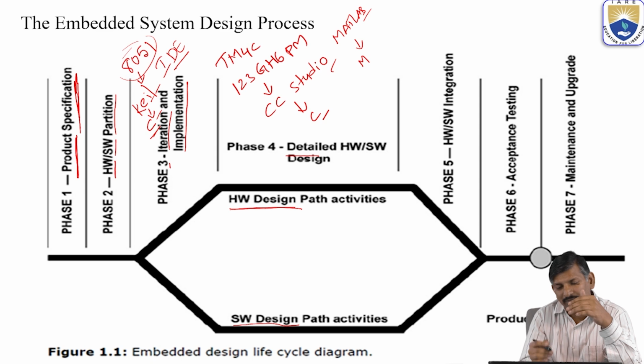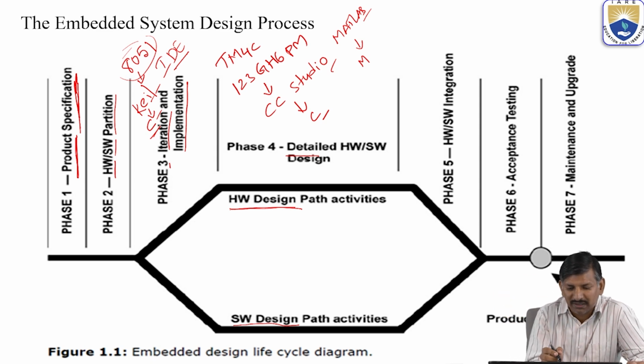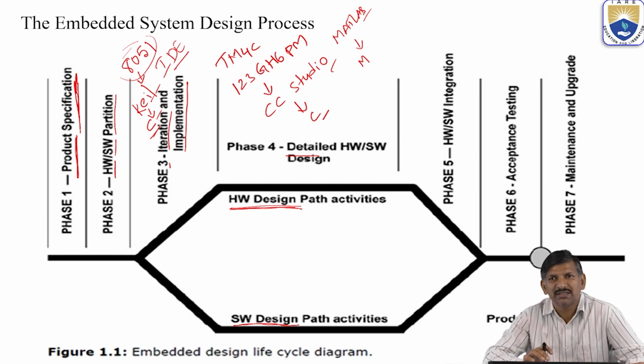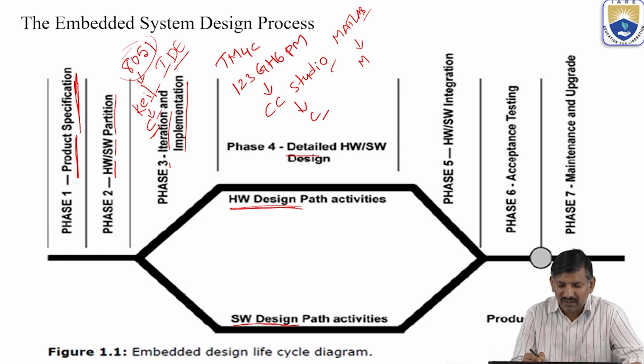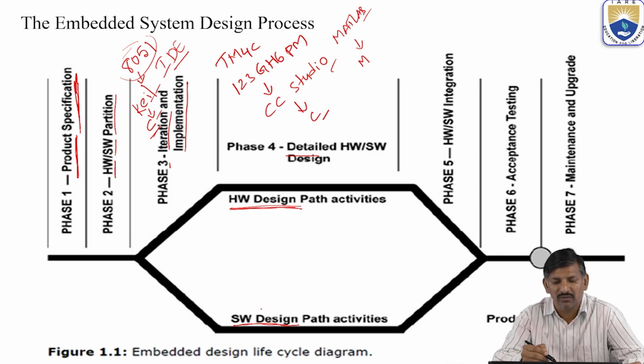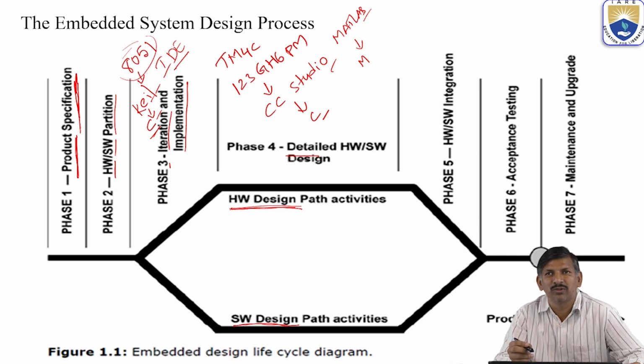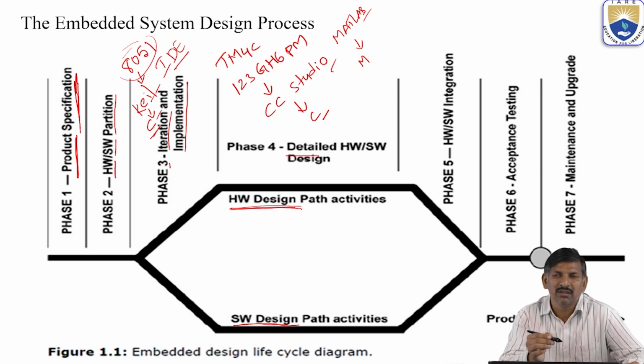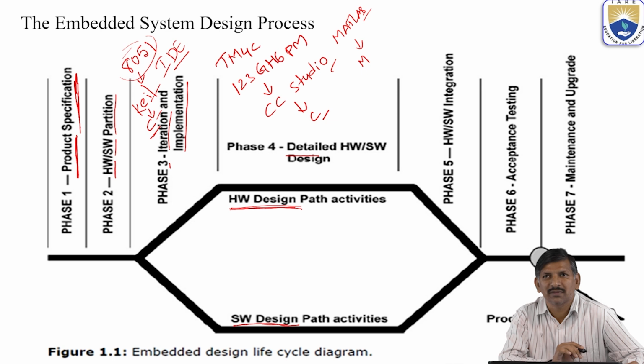Parallelly, if you are designing sequentially, it takes much time again. So at the same time, parallelly, I am designing the software design and doing the hardware design. Once both designs are completed, I am integrating the firmware or software into the hardware by using integrating tools like Prog ISP. By using Prog ISP, I can load this generated C file, the hex file, into the 8051 development board, using Prog ISP or some integration tools.